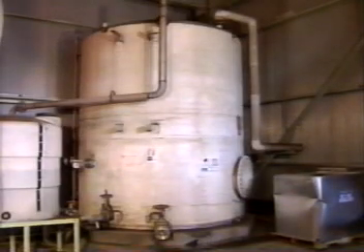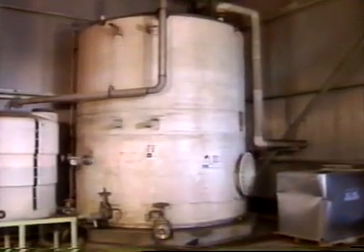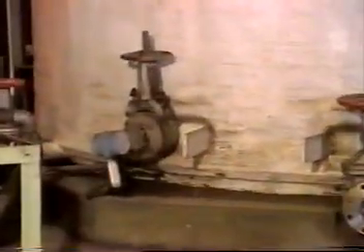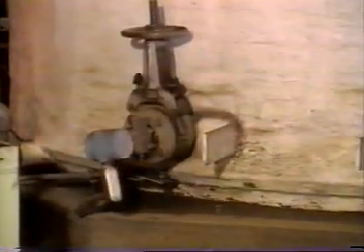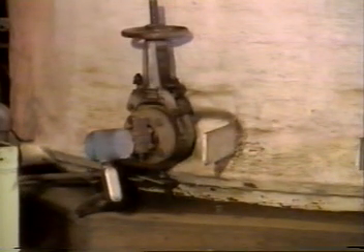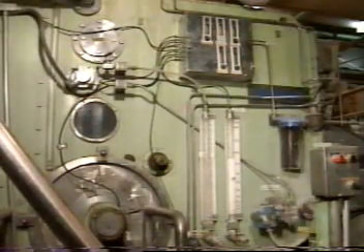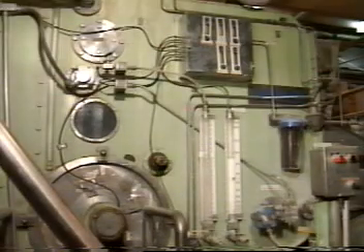This tank is partially filled with fluid. A transmitter senses pressure at the bottom of the tank and produces a signal proportional to the pressure. The instrumentation system then compensates for the density of the fluid and generates a signal proportional to the tank level. Such a system would not be accurate on a closed tank which is pressurized.